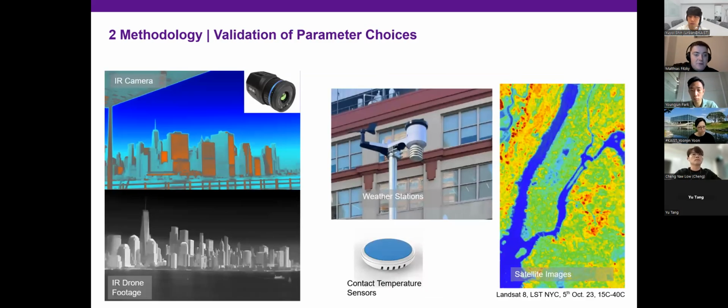Then we also apply a certain set of simplifications in our simulation. For example, we didn't directly model poles or trees or cars or whatsoever. I mean, trees are directly modeled, but not all of them. That is where we apply certain roughness parameters to certain zones. That's just an example of how we simplify certain things. We have to parameterize certain things because otherwise, if we model everything explicitly, the whole simulation would take forever.